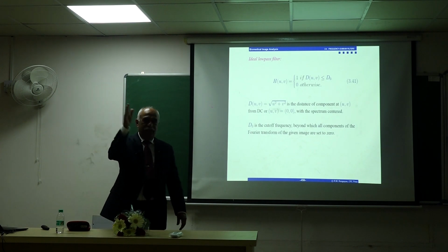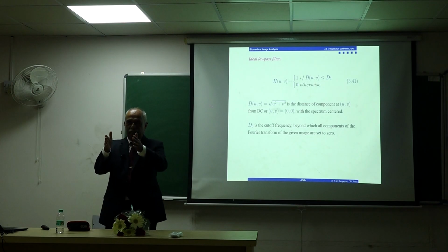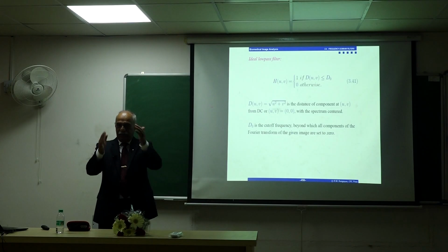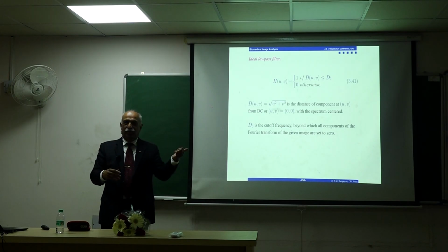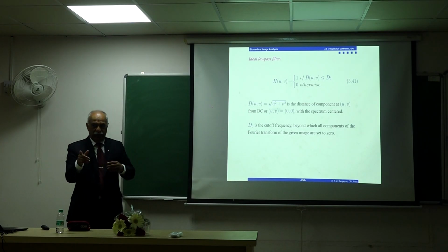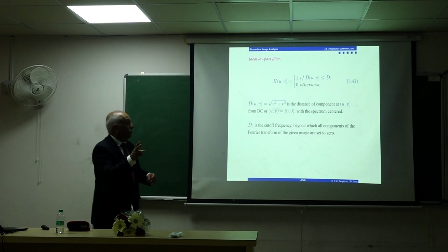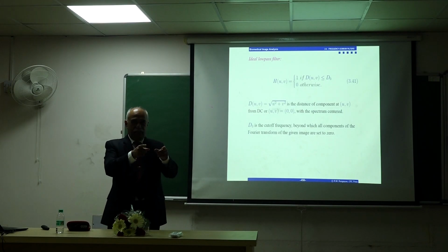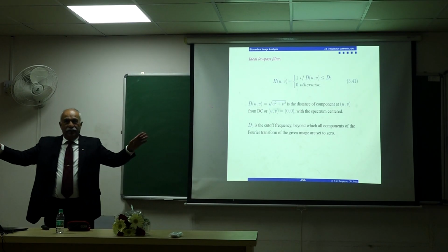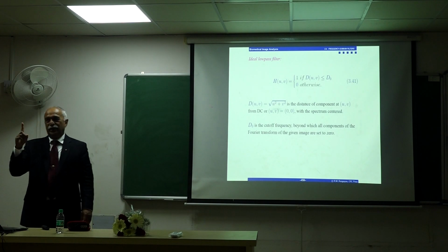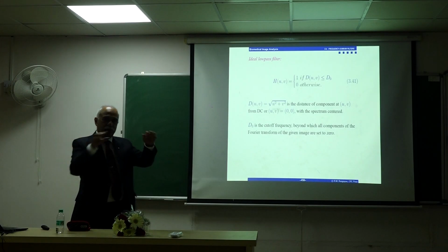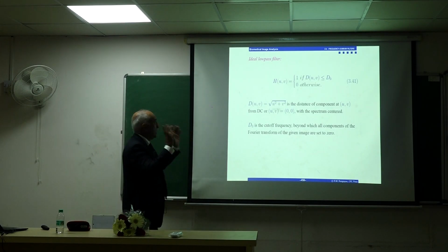When you have such a sharp transition and one of the signals is band limited, its Fourier transform cannot be limited. If you have a band-limited function, it is not time-limited or space-limited. If it is space-limited, it is not band-limited in the frequency domain. Like the rectangle function is space-limited, but its Fourier transform, the sinc function, goes forever. Right? And if it is an impulse in the frequency domain, it is band-limited, but its inverse Fourier transform is a constant forever, all space.